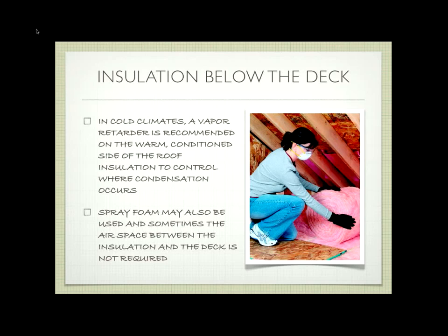It's a very specialized paper, so to speak. It's kind of a plasticky paper. And the way the weave of Tyvek works is that it allows moisture to pass through it in one direction but not in the other. So we wrap our buildings in Tyvek, such that any moisture that occurs on the inside of the building is allowed to pass through to the outside, but that water that's on the outside can't get through the barrier to the inside of the building. So in California, we do that because we can't really place where that vapor barrier belongs, because our seasons vary too much.